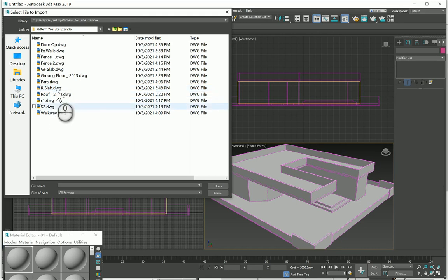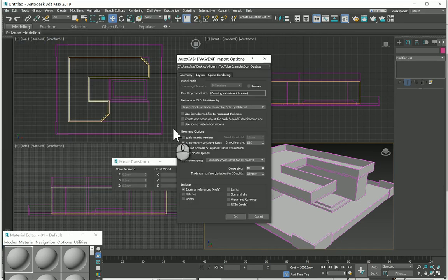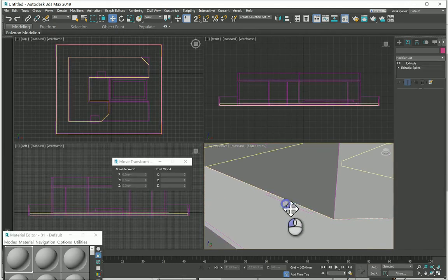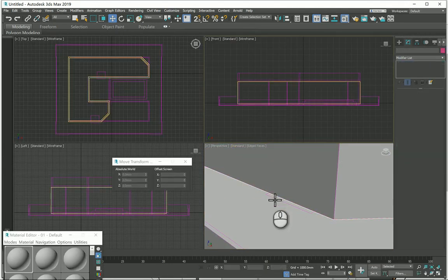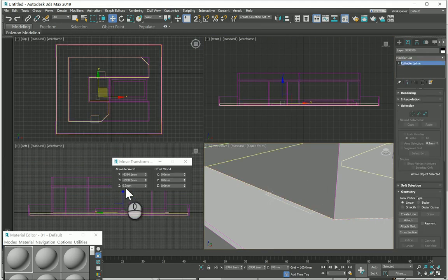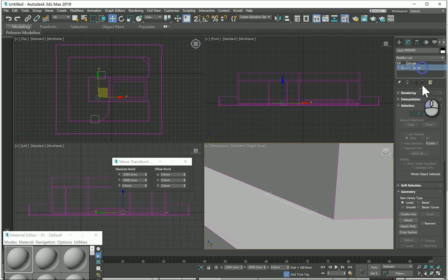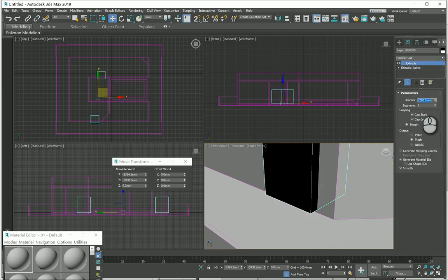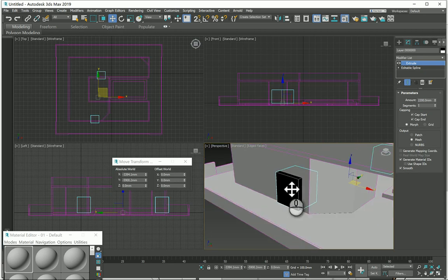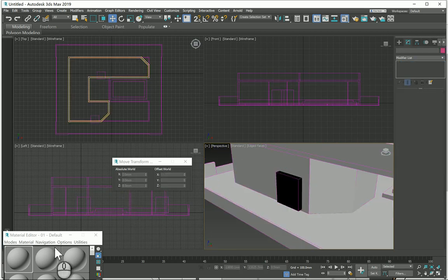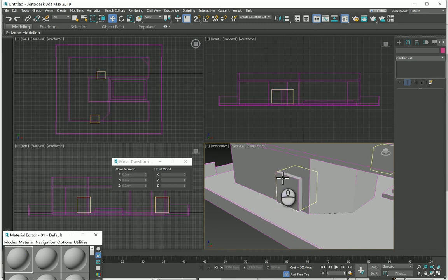So I'm going to go with the door opening, and the Z value should follow for the doors. Always follow the Z value for the floor finish, which is 0. So happy coincidence right here. Paste, and make sure that the height follows whatever you got in the section and elevation document. Now do not cut with the Pro Boolean unless you add material. Otherwise, you're going to have a black corner for the wall.